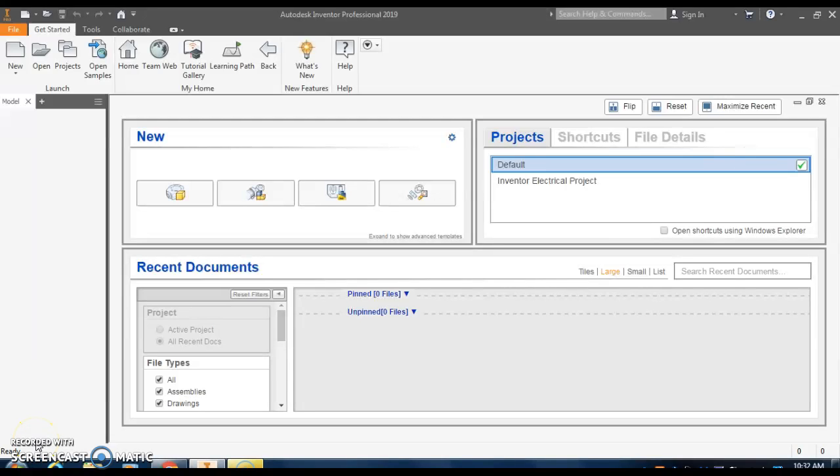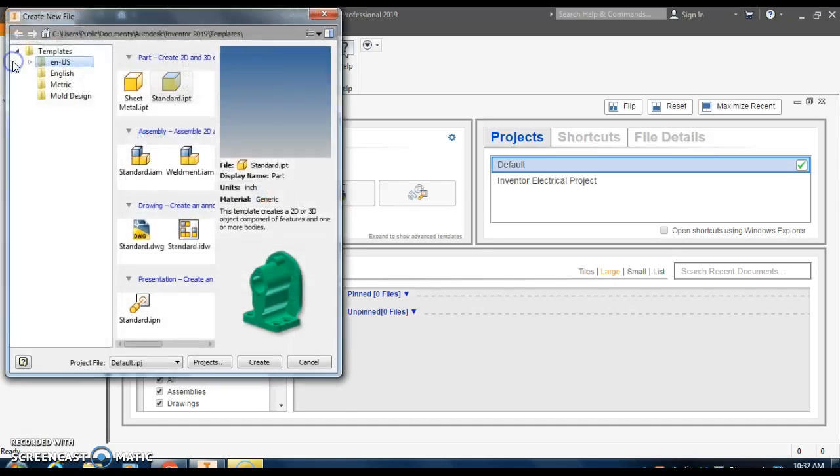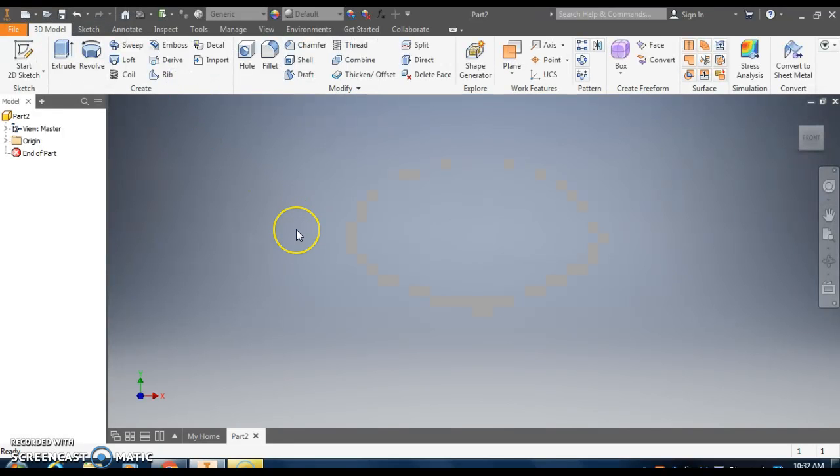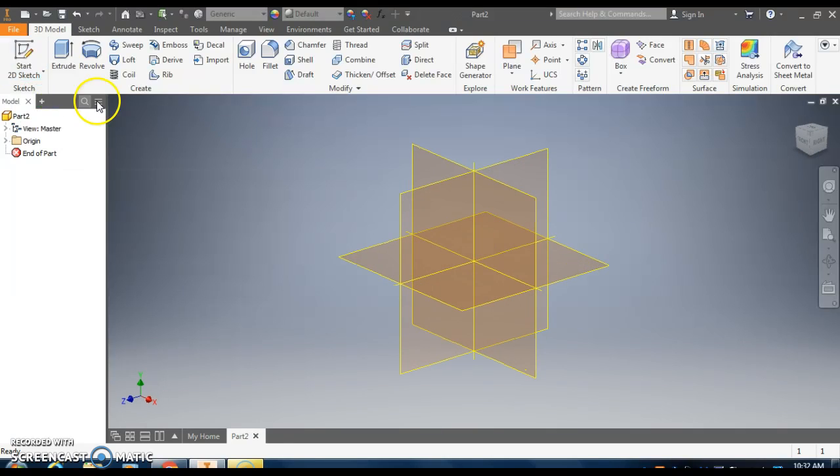Okay, we're going to draw cube number 5 in our isometric cubes drawing activity for Autodesk Inventor. First thing we want to do is select New, and we're going to create a 2D sketch standard IPT part file, so click on the standard IPT part file tab. Next, we're going to be creating a 2D sketch, so click on Start 2D Sketch, and again, Start 2D Sketch.